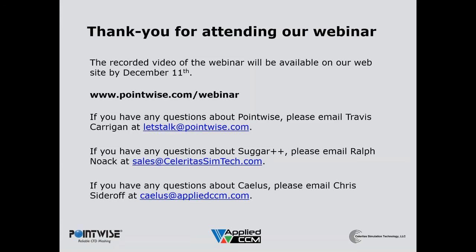I'll leave the higher order interpolation for structured meshes separately. For cell-centered cases, there's different ways of computing the interpolation weights. The best is to use the option which has a least squares procedure. There is an inverse distance weighting averaging, but I wouldn't really call that interpolation. I prefer the term just an averaging, and it's at best first order. And then there's another least squares kind of procedure in there. So the default is a second order kind of linear interpolation.